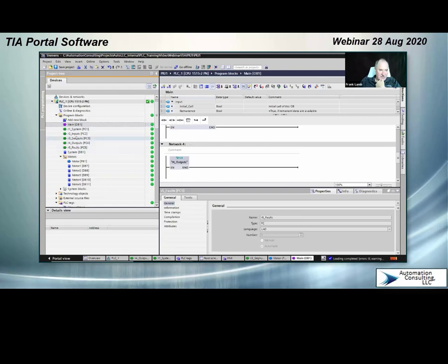The faults in the system bits matter less, right? I like putting my system first because it's easy to find, but it's very important as far as the scan that the inputs come before the auto sequence, which uses the inputs, and then the outputs, which the auto sequence often drives the outputs.